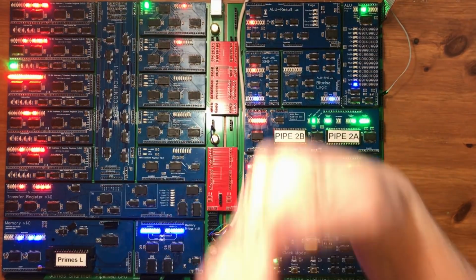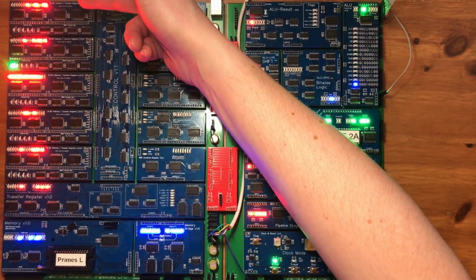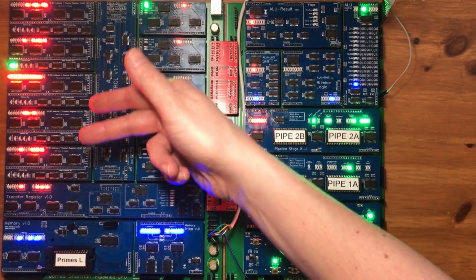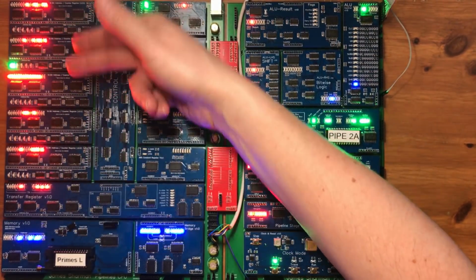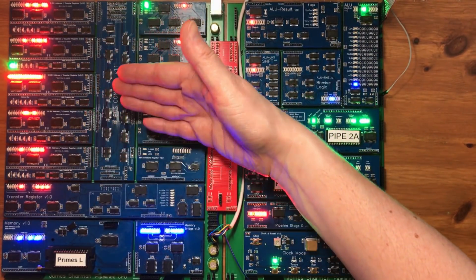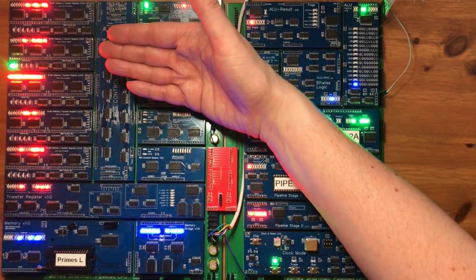So when an interrupt is raised, instead of dispatching instructions from the location of the current program counter, it becomes the interrupt program counter, and we pull instructions out from there and start executing them. And if the interrupt routine is very simple, it can just do a linear series of operations.